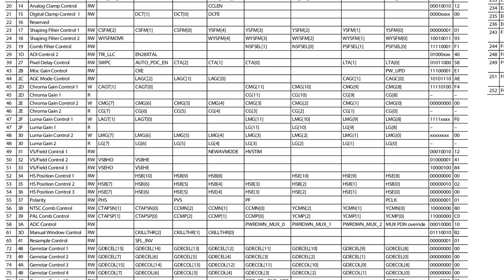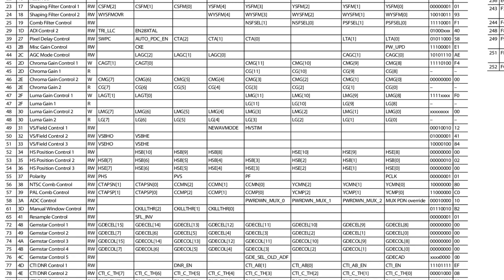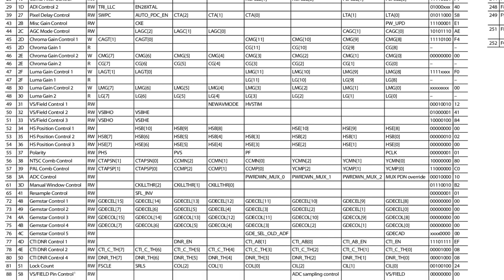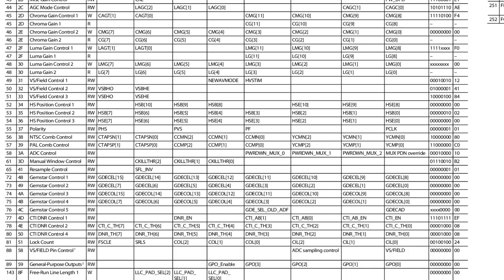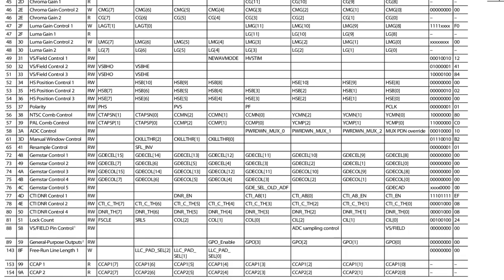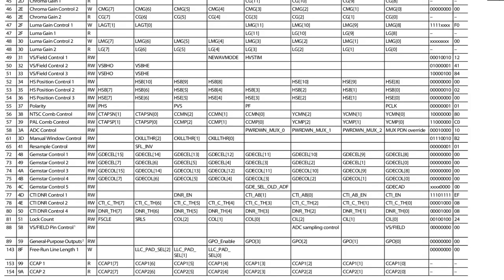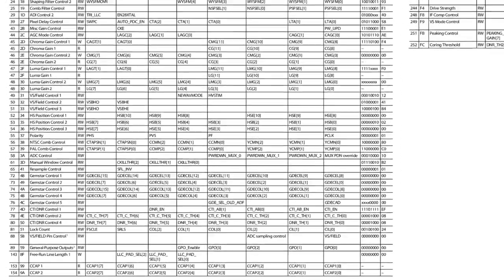Its basic documentation is 112 pages long, including 25 pages of tables mostly describing the encoding of the various registers. The explanation of what these registers are actually doing, such as settings for the NTSC comb filter for minimizing color artifacts, sprawls across the rest of the documentation.